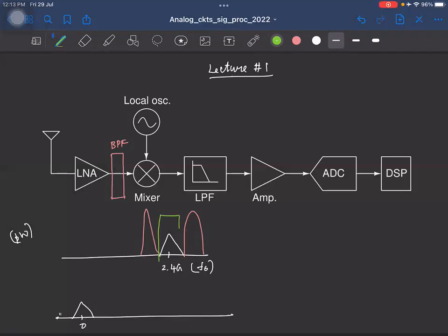And if you look at this bandpass filter, the center frequency is very high, right? For example, in this case, I have taken 2.4 gigahertz, but the bandwidth of this filter probably might be a few hundreds of kilohertz. Okay. And as it turns out, it is almost impossible to realize such a bandpass filter using LTI systems. And as we will see in the course, if we use LPTV systems, this is simply a cakewalk.